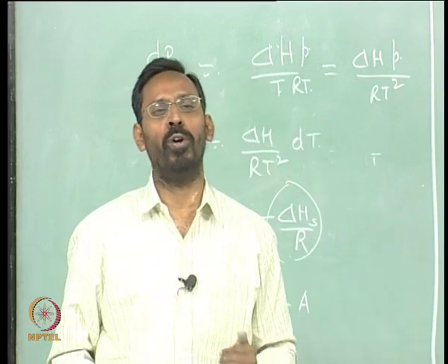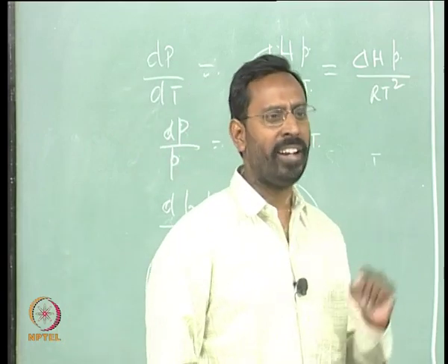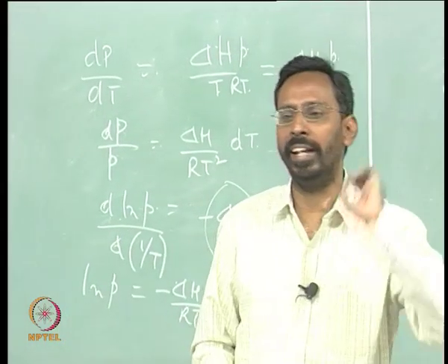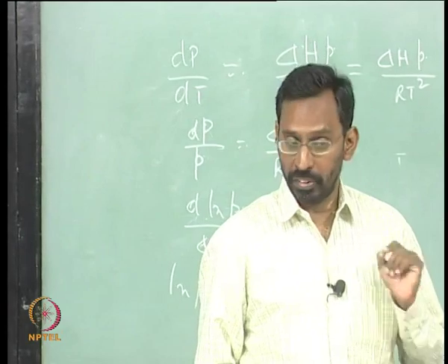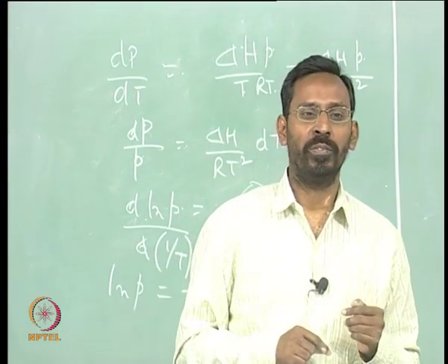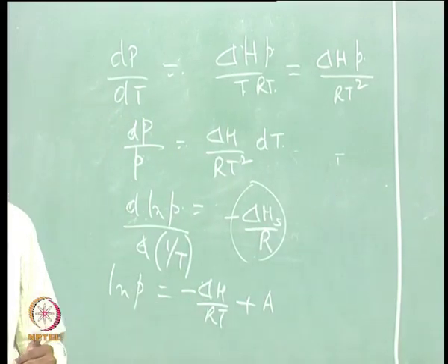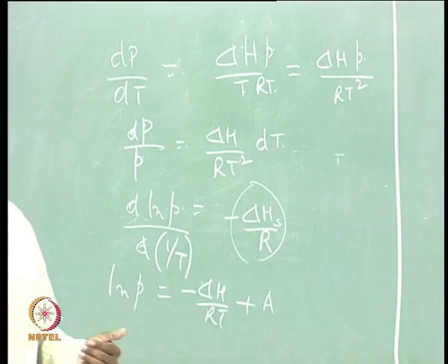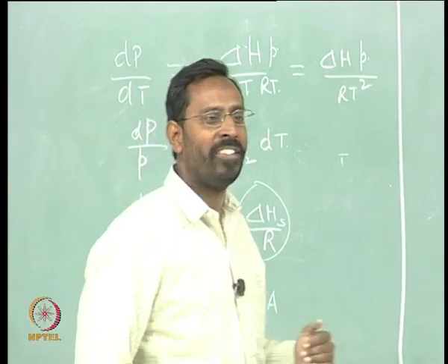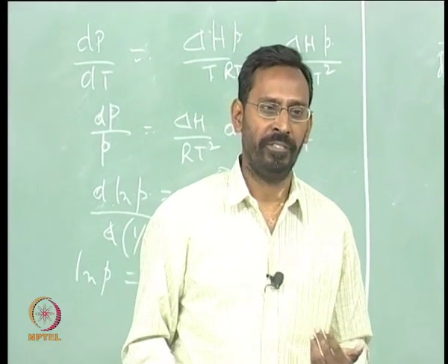Instead it undercools to a lower temperature and the transformation starts at a lower temperature. Exactly similarly, whenever I am heating a solid, in principle the melting point also shifts. The only difference is the shift in the melting point with the heating rate is not as much as the shift in the freezing point with a cooling rate.